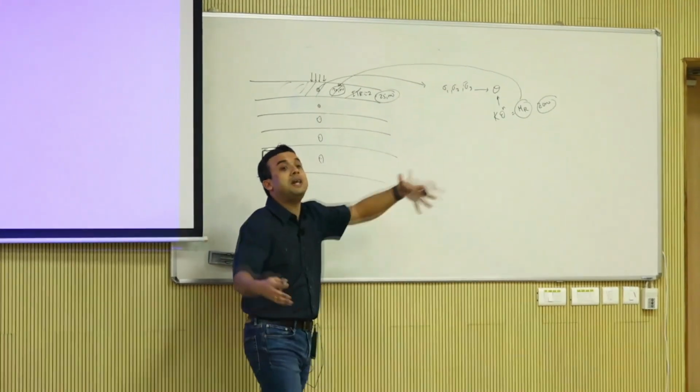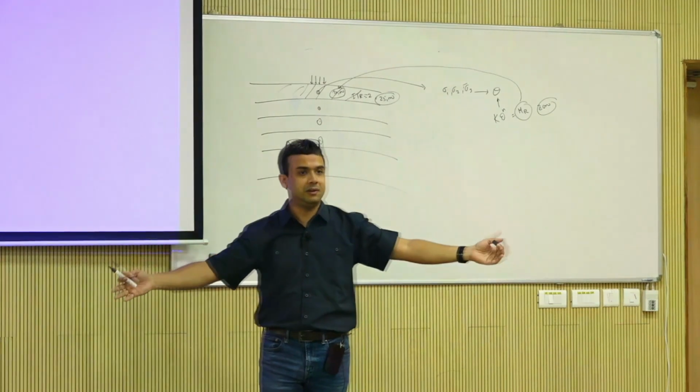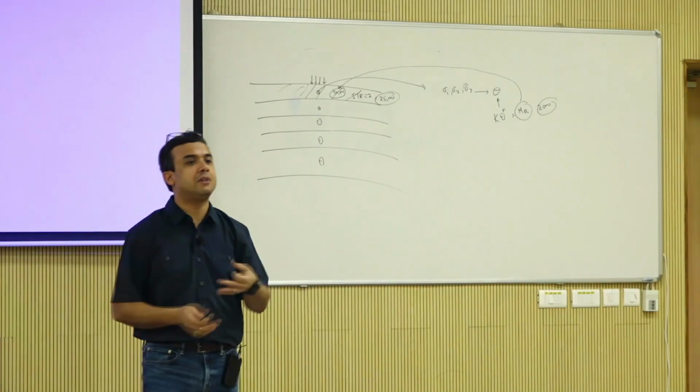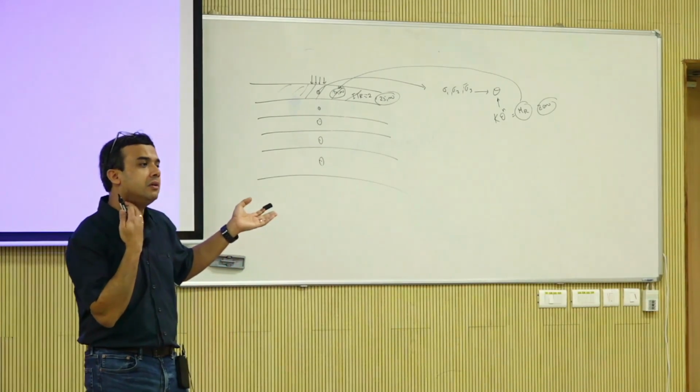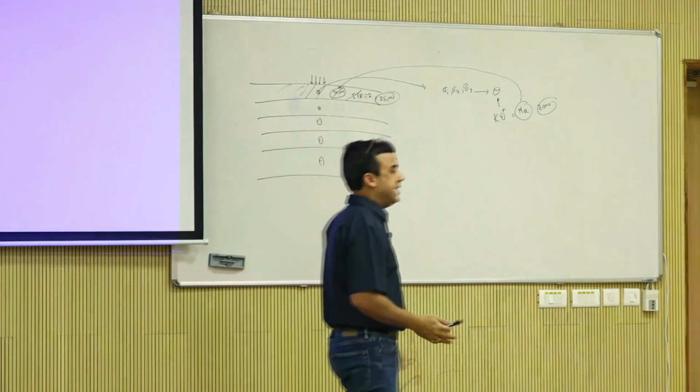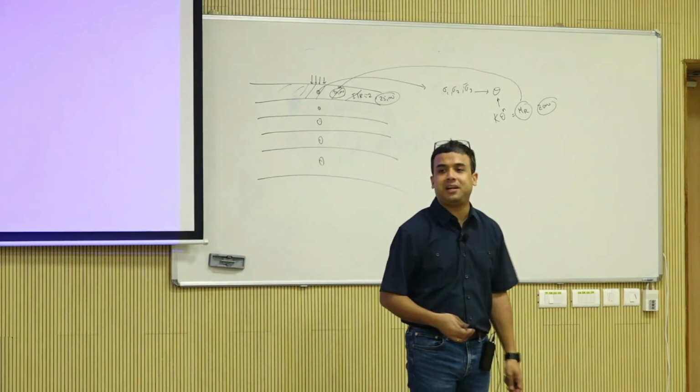When you have 24 inches of aggregates, don't just assign one value, subdivide it, run some analysis and figure out how this is going to go. Which model is better? Is K theta model better, Uzan model better, ABP?